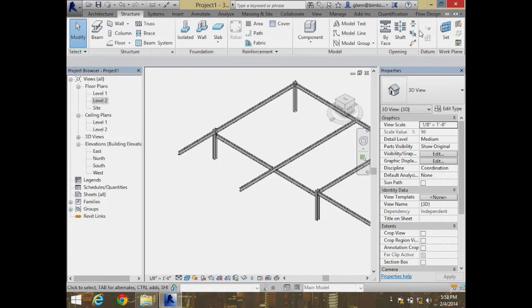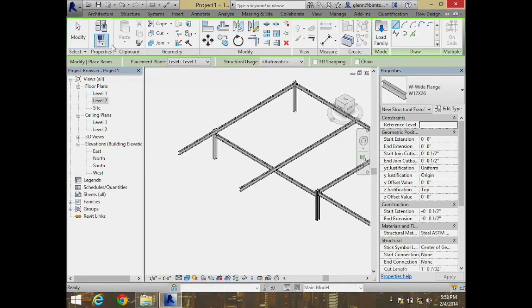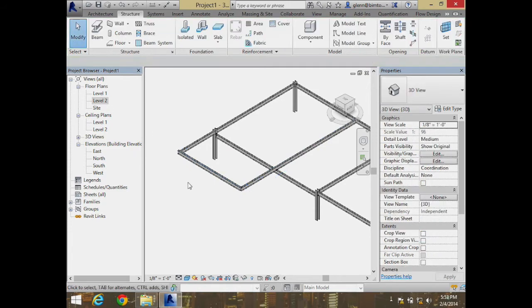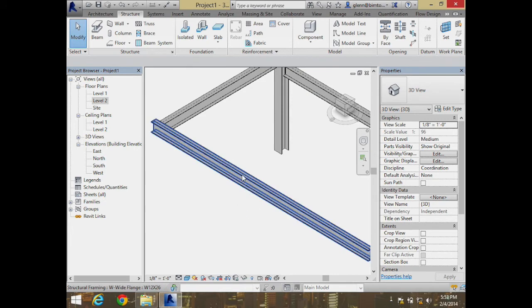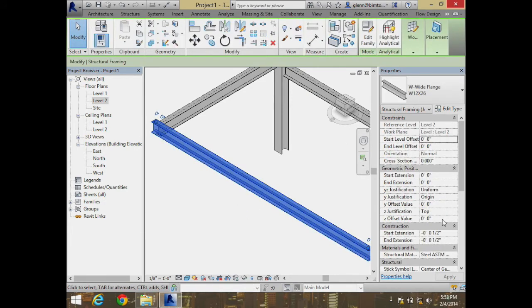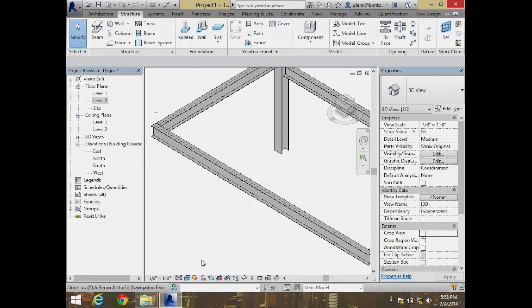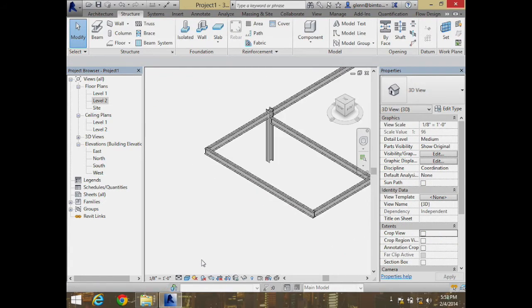And now we can go through and complete the structure out here by putting a beam that just connects. Let me do a 3D snap. Okay, let's come over here. Okay, and now we can adjust the height as necessary. By default, I think it's putting it in at the 0, so if I need to put that down to -5 inches, I can do that just so it's all level in terms of being underneath. Okay, and now we're in pretty good shape. That actually will go ahead and support the cantilever.